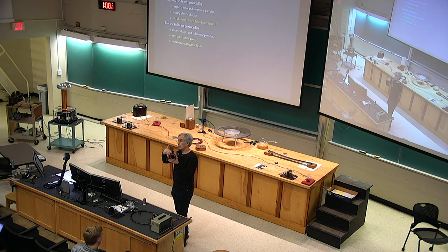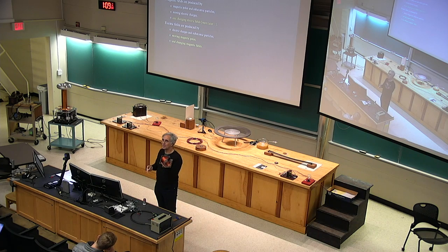The electric field will push them in the direction they're moving. It'll do work on them. They'll gather energy. They'll come out of the coil having accumulated energy per charge, also known as voltage. The voltage will go up. We'll get a voltage rise in the coil. And the coil is connected in a circuit to the light-emitting diodes and nothing else. They'll light up. Okay?